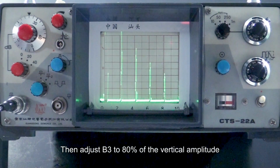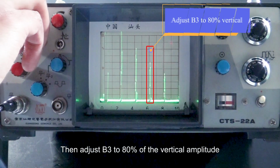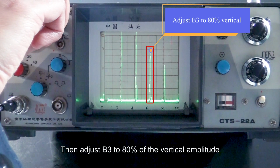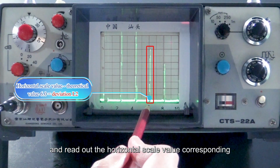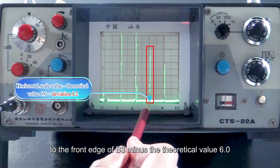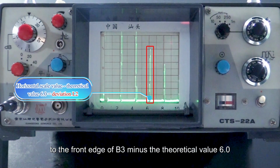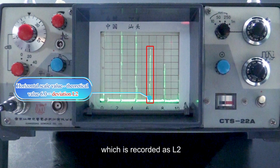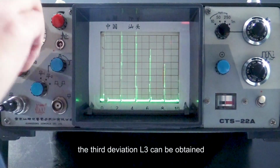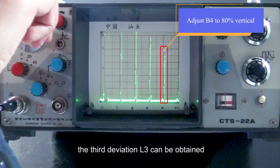Then adjust B3 to 80% of the vertical amplitude and read out the horizontal scale value corresponding to the front edge of B3 minus the theoretical value 6.0 to obtain the second measurement deviation, which is recorded as L2. By analogy, the third deviation L3 can be obtained.